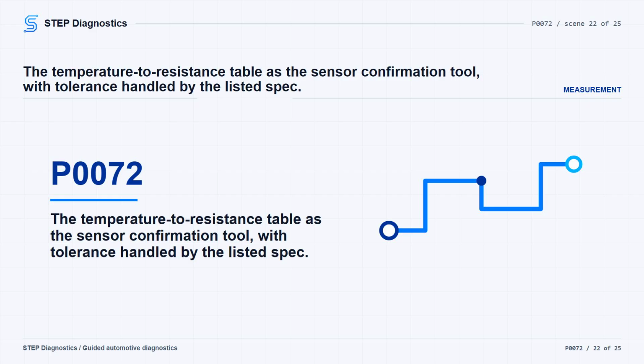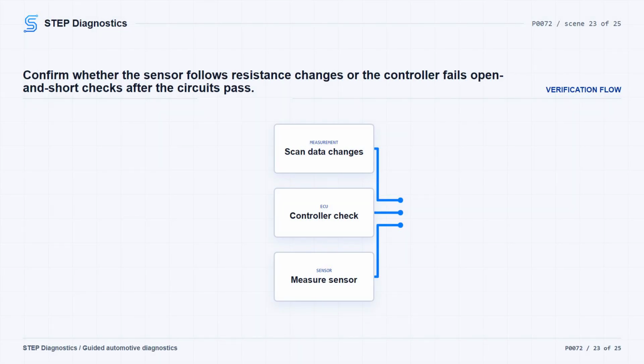25°C/77°F/9720 ohms; 30°C/86°F/7780 ohms; 35°C/95°F/6370 ohms; 40°C/104°F/5200 ohms; and 150°C/302°F/181 ohms, highest possible temperature reading. If a temperature table is available, dial the test tool to a table resistance value and watch the scan tool for the proper reading while you vary resistance.